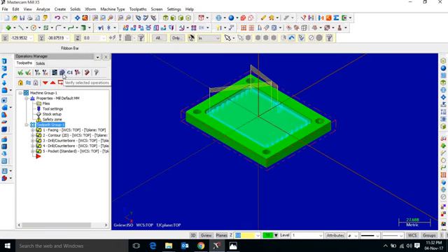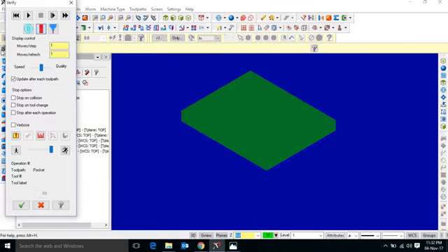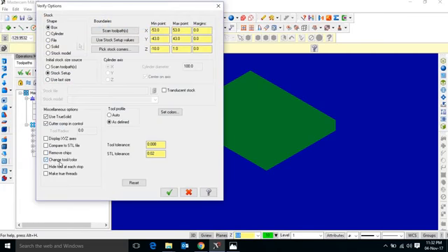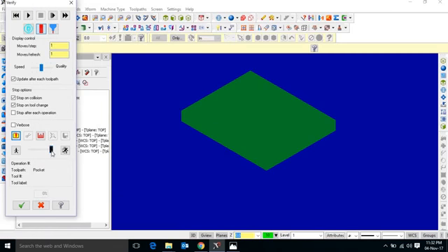There is also a verify selected operation tool in the operation manager. Click on the verify tool, select stop on tool change. So after each operation we know that the first operation is created. Click on the stop on tool change. Stop on collision: if there is some collision, the machine detects it and stops the operation. Select this one, change the tool or color. Okay, we reduce the speed by using this menu. So we go down to minimum speed, medium speed.